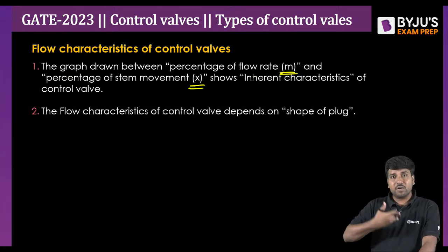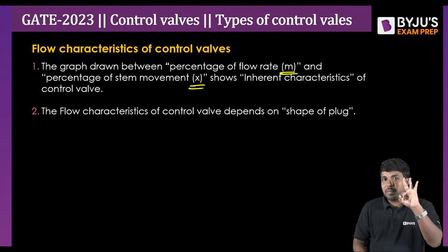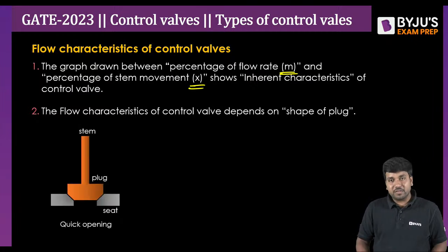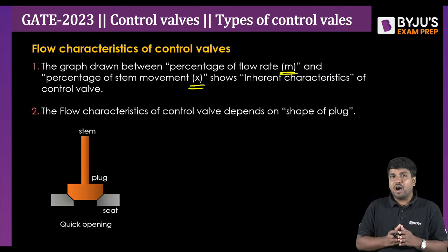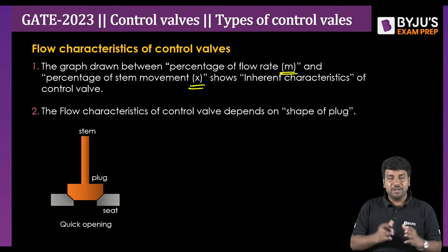And in the process of defining the shape of the plug, we encountered 3 different plugs, or 3 different structures, isn't it? So the very first one is the quick opening valve. We have seen how sensitive this is. For a small stem movement, we have seen a great amount of fluid flow rate.